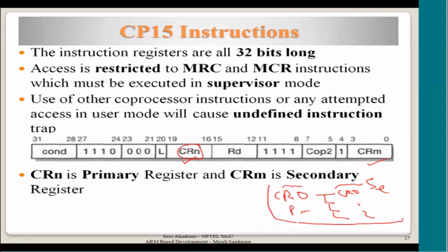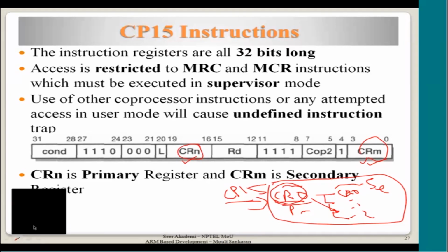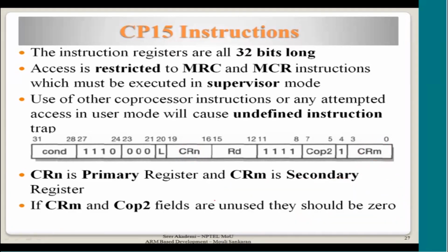See, effectively there should be a space provided in the controller which is behaving like coprocessor 15. So when an operand with the CR0 comes, it will know that any number mentioned here is actually referring to another set of registers in the system. So it can always be built in such a way that when you are writing to CR0, under CR0 one register, you can always pass two parameters and then write into that. So that is what is being done in implementing the MMUs and MPUs as a coprocessor.